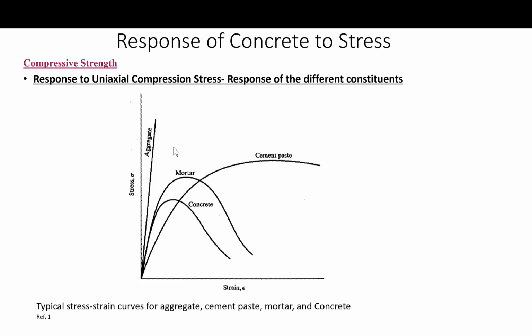Okay, so the heterogeneous nature of concrete not only affects its behavior under low stresses, as we discussed before, but in fact dominates the behavior of concrete at all levels of stress. So, as we established before, it is well known that much of the physical nature of the response of concrete in compression can be described in terms of microcracks that can be observed at relatively low magnifications.